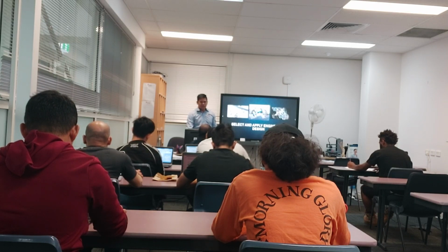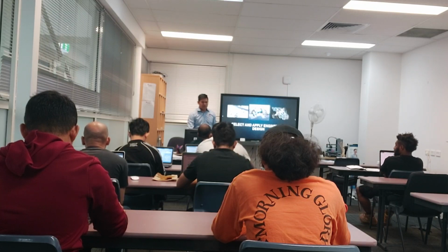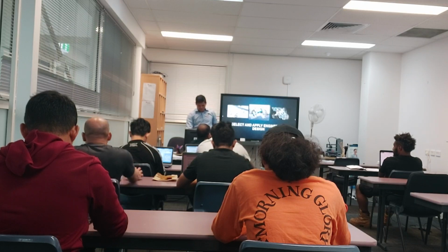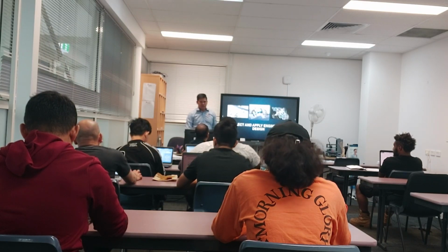Once that is done, you have already finished close to 80% of your design. Then once it is manufactured, you assemble it and do the testing and inspection. Once it passes, you take measurements of the input power, output power, speed, and all that. You run the gear for, say, 10,000 hours, and if it stands up to that number of hours, you have passed the design, and you can release the design as a standard product.